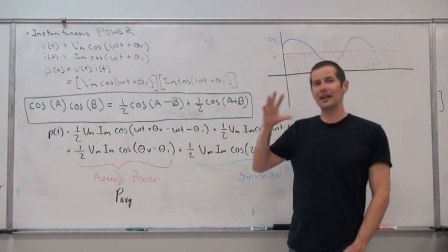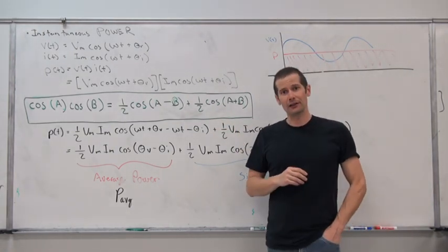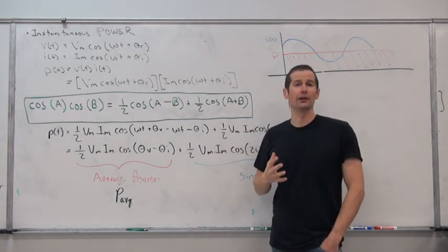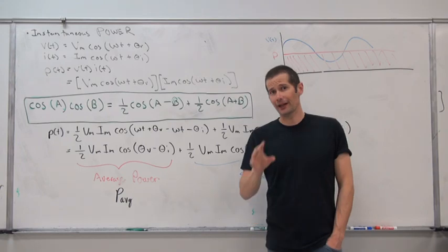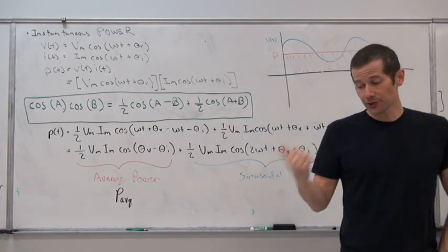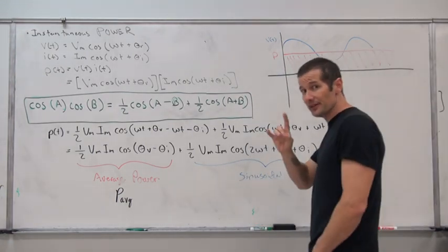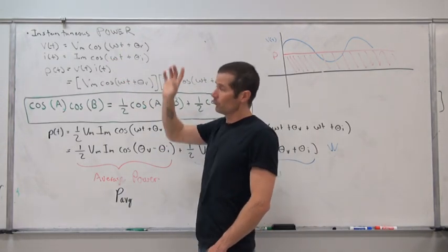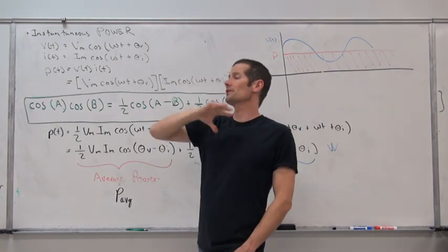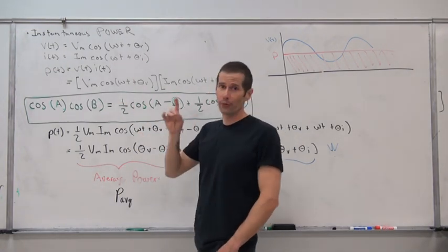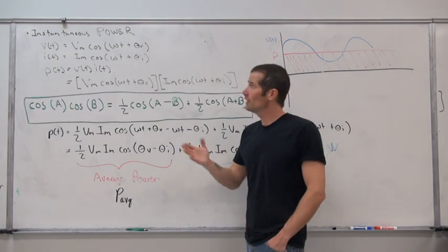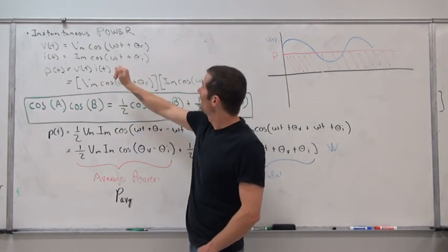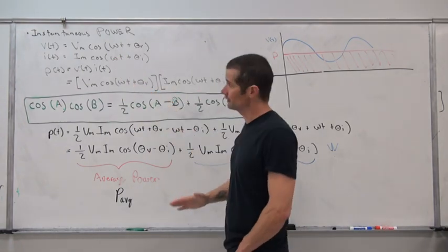However, when we take instantaneous power and consider that with the introduction of alternating current within the circuit, then as we have said before, if we introduce a voltage that is sinusoidal in nature with an angular frequency omega, whatever the voltages across elements or the current through the elements end up being will also be of a sinusoidal nature, the same cosine waveform and the same angular frequency.